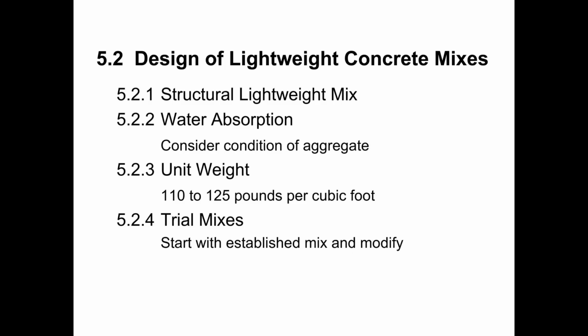Okay, so it's a lot quicker just to get a template mix design from your aggregate supplier, and it takes a lot less time on your part. And oftentimes that is a better starting point than going through the development process would be. But once you have that mix design from the aggregate supplier, trial batching is still going to play a pivotal role in your mix design development process.